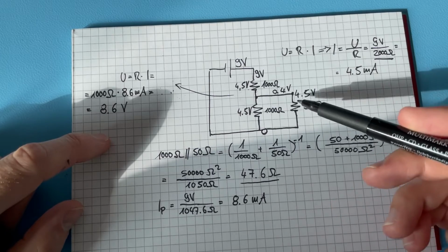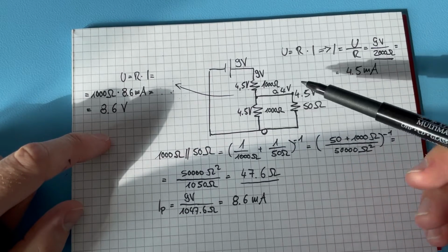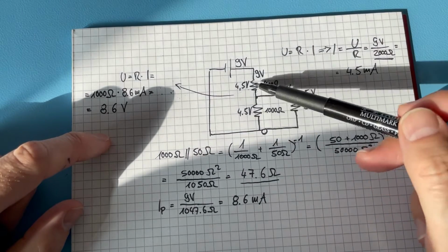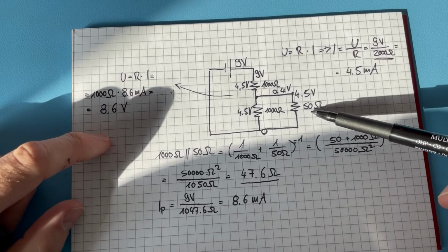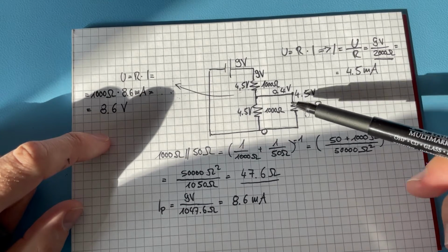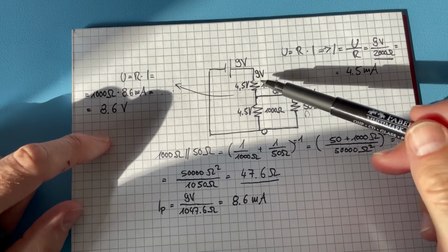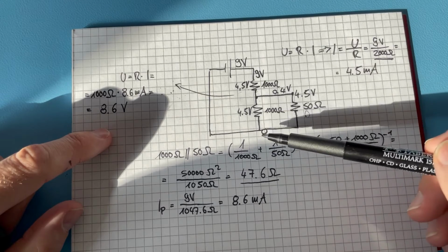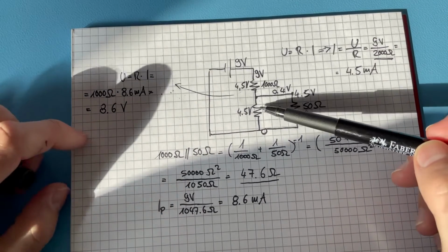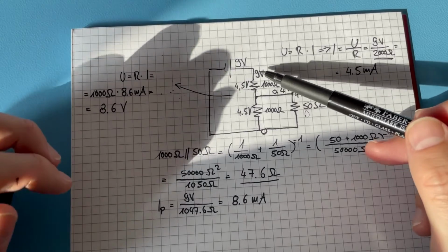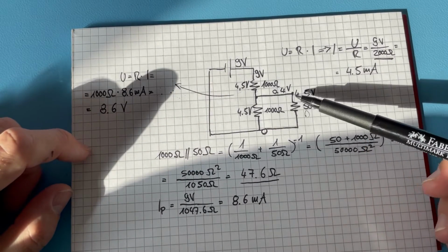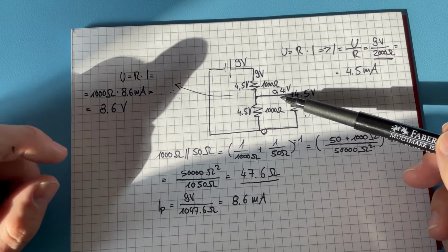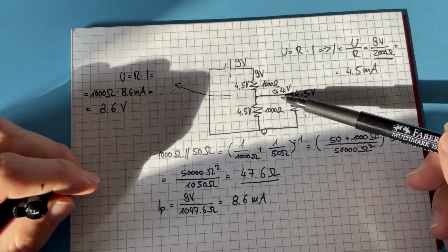But then once you attach a load to such a simple voltage divider, you change the whole constellation and the whole resistance of the second part, and you lower it, as in this example, oftentimes you lower it, and then you get a bigger current flowing through the whole constellation, and when you get a bigger current flowing, you drop more voltage at the first resistor, and you're left with something that you really cannot use, you don't want.